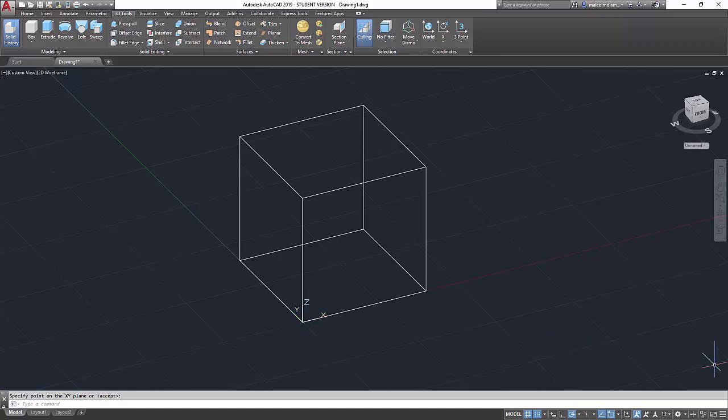So the next thing we have to do is to place the spheres, and I've chosen spheres for this particular thing. We could do other shapes, but the sphere, no matter whereabouts you put it, because it is spherical in shape, if we place its center point on any of these faces, we can later extract them to form a semi-hemispherical dimple.